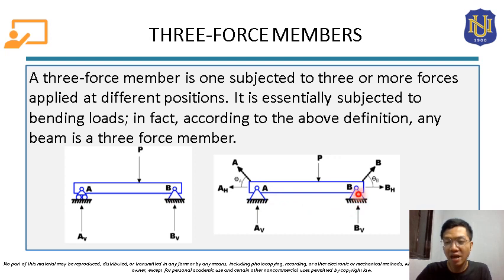That bending action should be countered by the supports. So the supports should provide forces that counter the bending action of the beam. These forces will be reaction A, inclined theta A from the horizontal, and reaction B, inclined theta B from the horizontal.